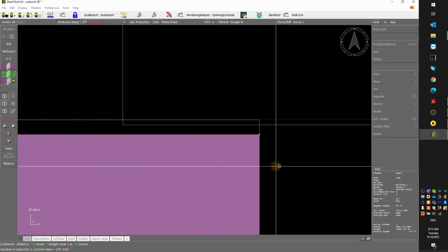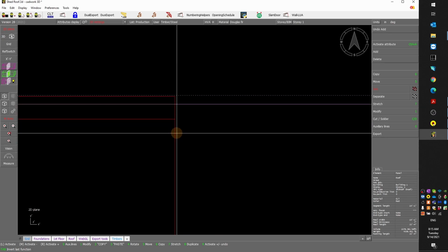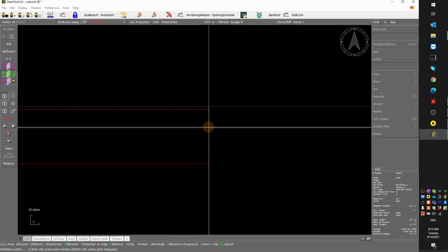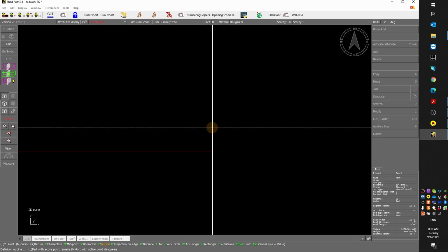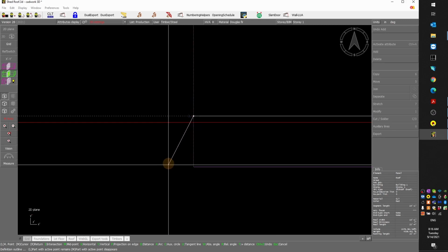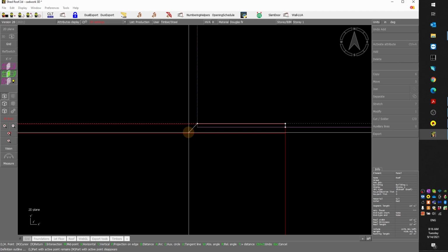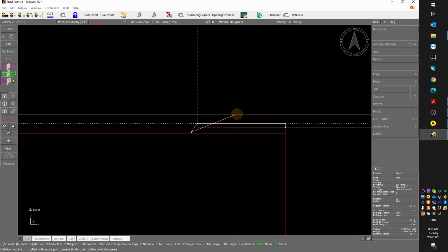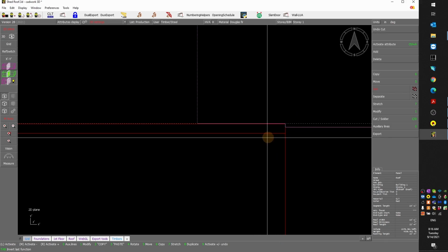there we go. And here I'm gonna cut this panel, so CC to cut contour, CC, from here in Y here, and I go back to this point here, and here I get out, and the goal is to make sure the portion I want to cut out is completely within the point, so I don't need to go back to the first point, but just here right click, and now it's done.